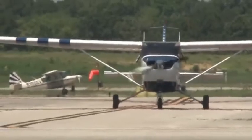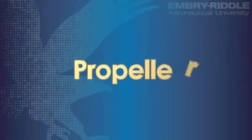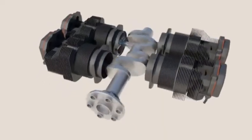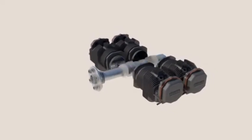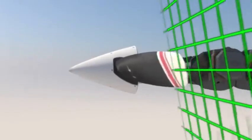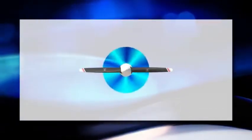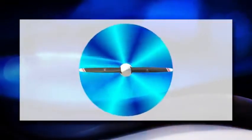Now that we have a better understanding of how an engine basically works, we will examine what creates the thrust for the airplane to fly. Remember that as the combustion occurs in the cylinder, the pistons rotate the crankshaft, which directly drives the propeller. The propeller, when closely examined, is actually twisted. This is simply to create equal thrust along the propeller blade. Since the propeller rotates around its hub or center, the further the propeller extends out of that hub, the faster it spins. To create equal force throughout, manufacturers twist the blade.